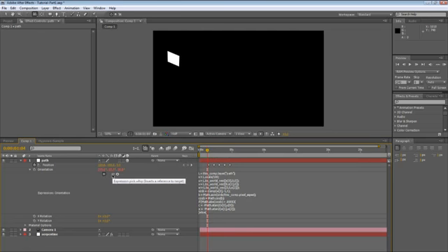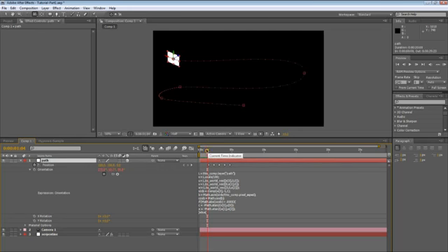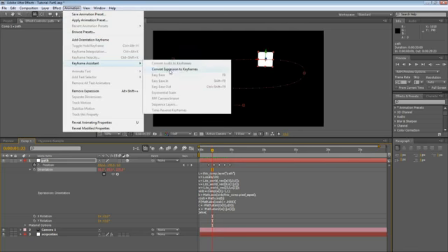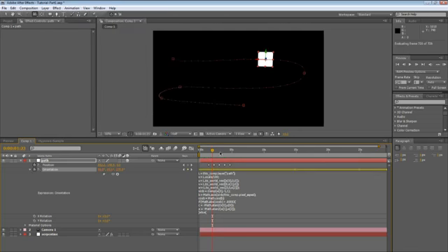So my thought was that if I grab hold of these numbers, then I can change only the problematic areas, instead of creating all those orientation keyframes for the entire motion path. I can just go to the point where there is a problem and solve it locally, and that's it. So here's what you want to do. You go to the orientation, select it, choose animation menu, keyframe assistant, and convert the expression to keyframes.